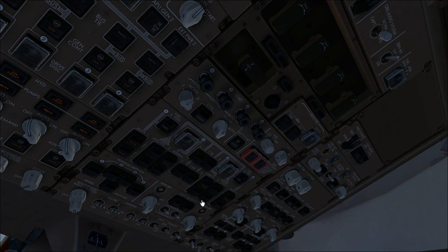Anyway, follow the tutorial, read the operation manual and the amplified procedure for the cruise. You will find all the information here. They are pretty straightforward. Now we have to check all fuel pumps are off. They are all off, and we have to check the main pump press lights illuminated. That's fine. The main 1, 2, 3 and 4. Of course, I said those 2 lights are off because we have the APU started up and the DC pumps for the APU are on. In fact, we have to check the override 2 and 3 pumps and center pumps press light is extinguished, as you can see, and the stabilizer pump press lights are extinguished, and this is checked.